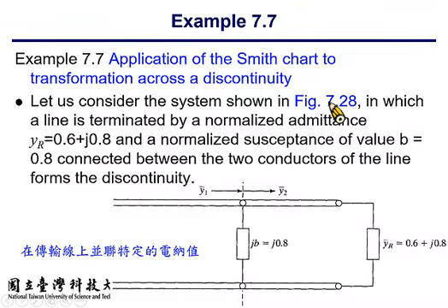We should write in lowercase r. And what you should do next is draw the constant SWR circle. So this is the locus of the reflection coefficient by moving to the different position on the transmission line. Okay? Questions? How long does it take to rotate one full circle? Half a wavelength, 0.5, right?